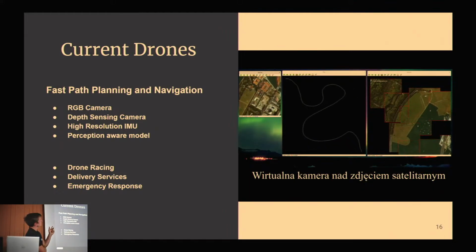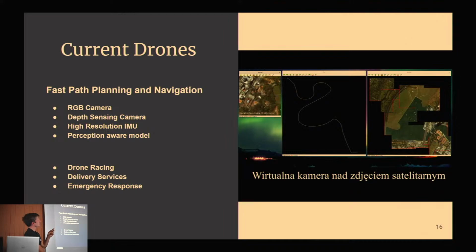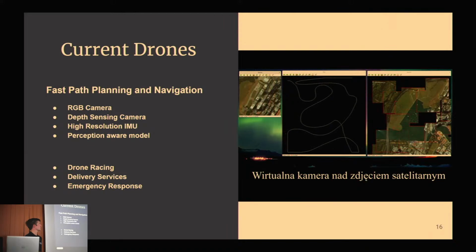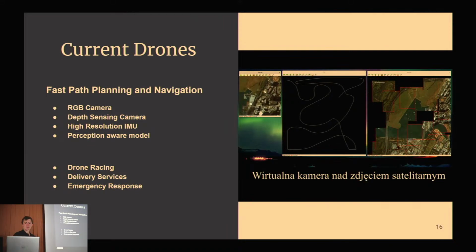In the center we can see the path that our algorithm detects from the movement of the camera. It was also able to make a 2D map from all the images received during this process. So that's basically another way to make a drone able to locate itself in a 3D environment.